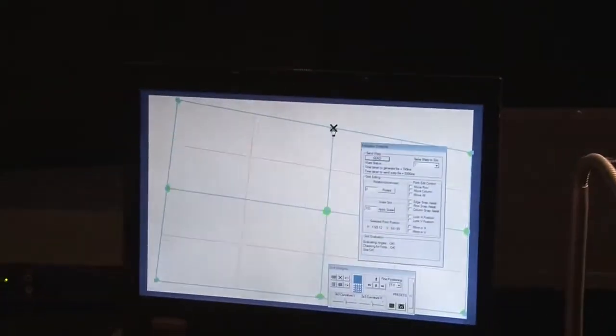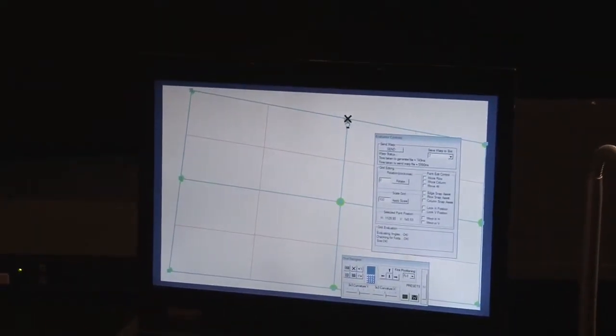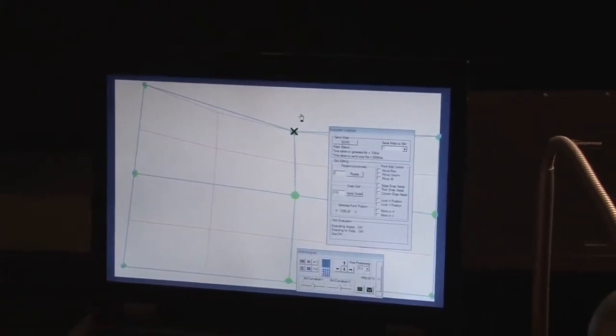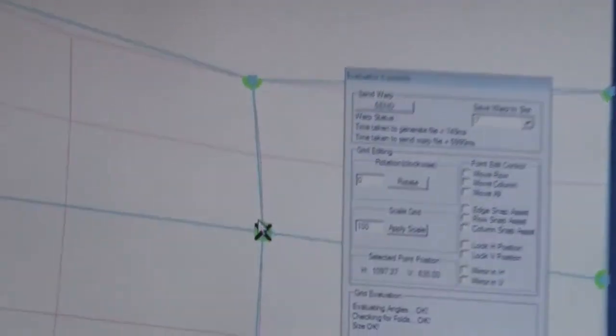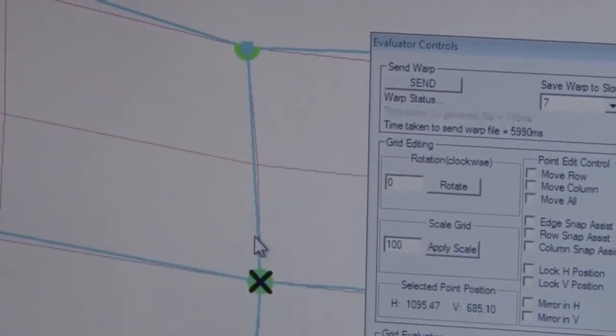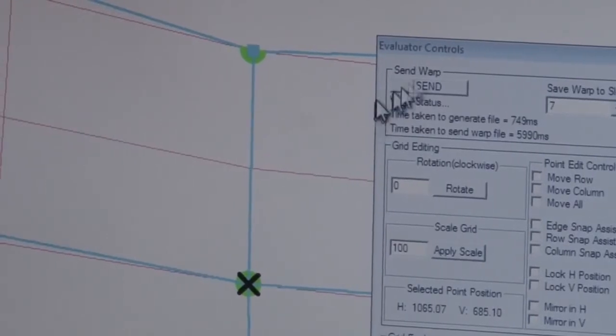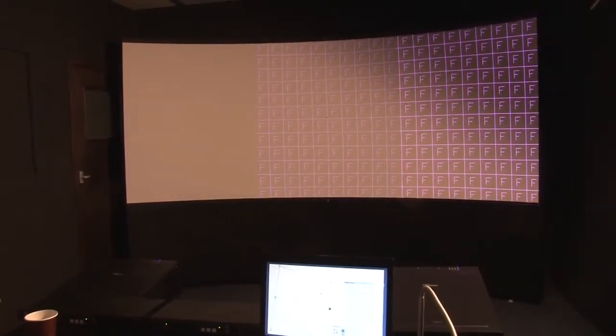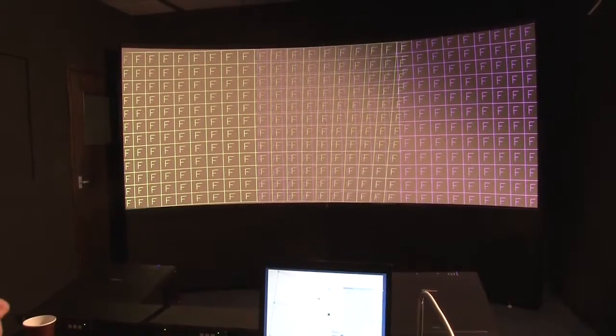At this point we're going to upsample the grid because we need more control points. So now we've gone from having 4 control points, just the corners, to having 9 control points, which gives us points centrally in the image as well. Now you can see the image is starting to come together. The scaler is just redrawing the picture. You can see it's starting to square up now.